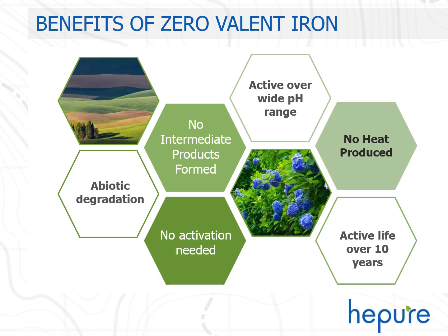There is no need to precondition the aquifer to provide activation. pH effects are minimal, and it works over a wide range of pH. There is no heat produced, and the most important is ZVI has an active life of over 10 years.